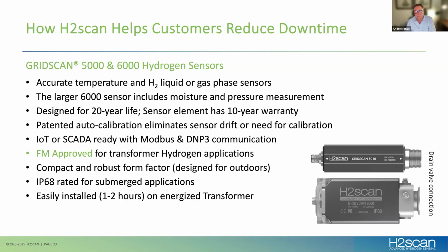If you elect to install it in the gas space, one sensor is all that's required. And how many sensors can be connected to one transmitter? At this moment, it's a one-to-one relationship, and we're busy working on a meshed radio system so that we can connect all the sensors in the substation to one transmitter. But as of today, to get up and running immediately, it's a one-to-one relationship. That same modem also provides the power these sensors require, so that's some of the work we're putting into the mesh radio as well.